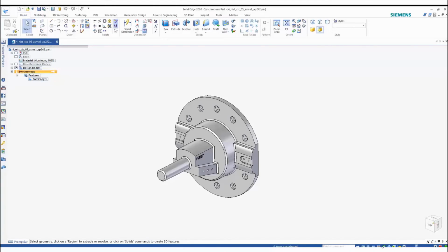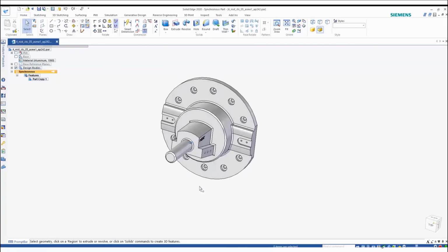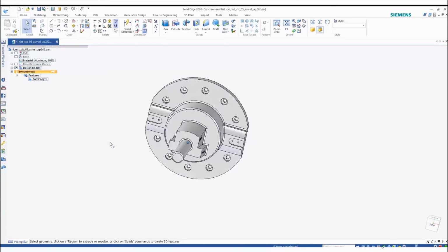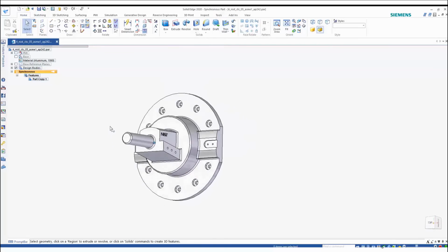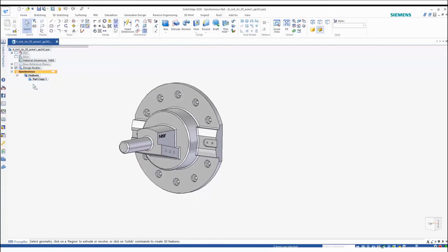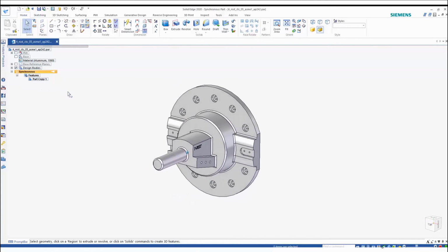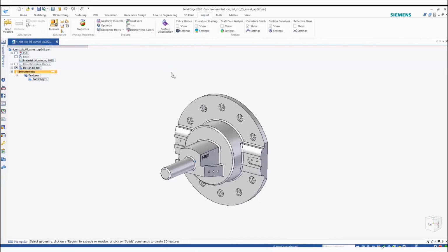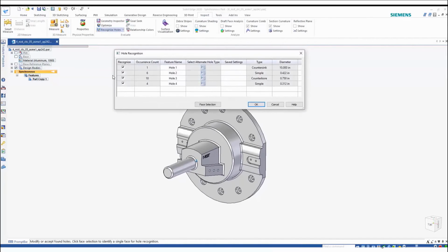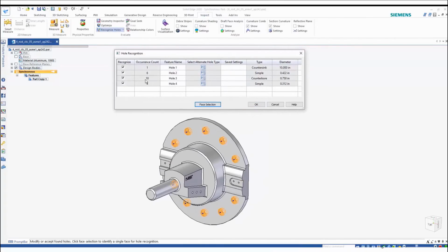One thing to note about imported data is that it doesn't come into Solid Edge automatically with intelligent features. This can be seen in the Pathfinder. If certain information, such as hole callouts, needs to be displayed for model-based definition and be accurate, this information needs to reside in the 3D model.